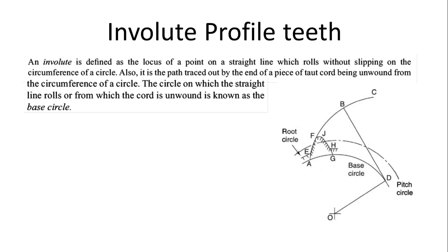The arc will be traced in such a way that it opens in the form of a rolled sheet. If you take a paper, roll it, and then open it, you get the entire path, the entire curve. In the same way, the path is traced on that teeth profile, and the same thing is generated throughout the arc, from A to F. In the same contour, you can get the path from A to B, then upward to C, and that should be taken from the base circle.